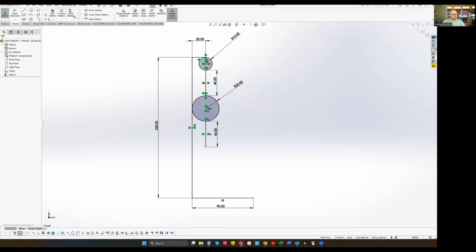The next sketch tool we're going to use is a new one, the 3-point arc. You can just click on this point, somewhere in this area. You don't want to be directly above, snapping vertical to this point, because then it'll create a vertical relationship. So let's snap somewhere right over here. And then the third point allows you to manipulate the radius of that arc.